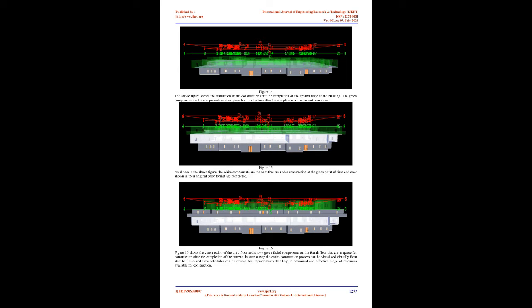We then rebuild the task hierarchy in Navisworks Manage, which means transferring the schedule from the CSV file to the software. Then they are linked to the respective sets created earlier for simulation. The task type is set as construct. The simulation is carried out after linking each set with their respective tasks according to the following settings, where playback duration is 20 seconds and interval size is 15%. Once the settings are fixed according to choice, the simulation is carried out. The interval size denotes the time period for the next activity to start. This can be set according to different units such as percent, days, hours, minutes or seconds.